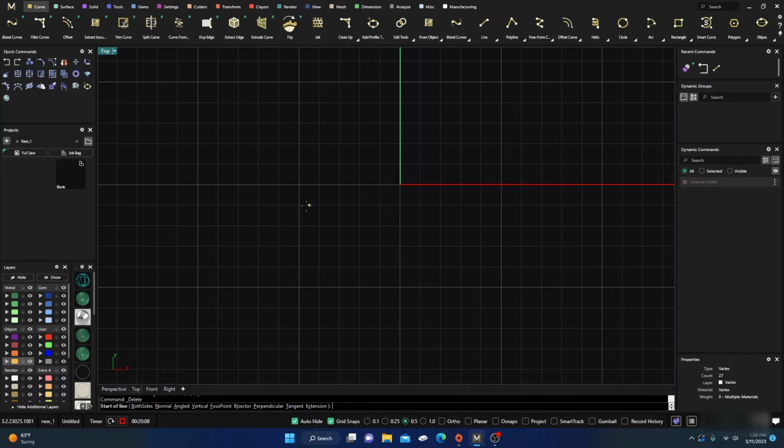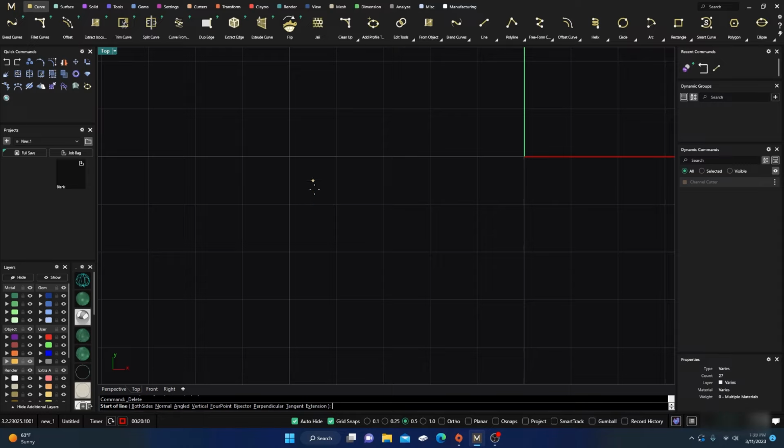So now you can see it's snapping to each 0.5 millimeter wherever I go, even in the center, wherever I move it. Or you can change it to 1/4, which takes it to 4, and again it goes any direction you want, or you can change it into 1, right? So really small increments, or you can just have none.